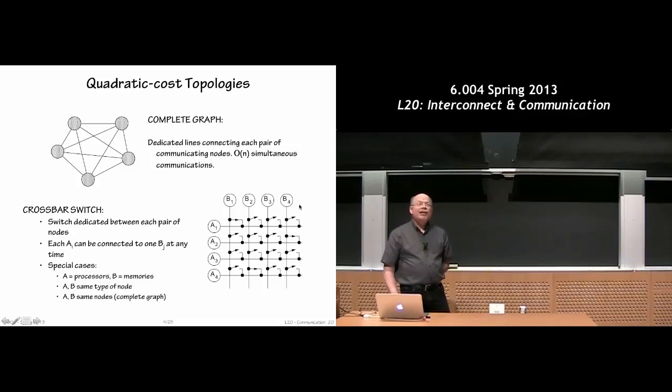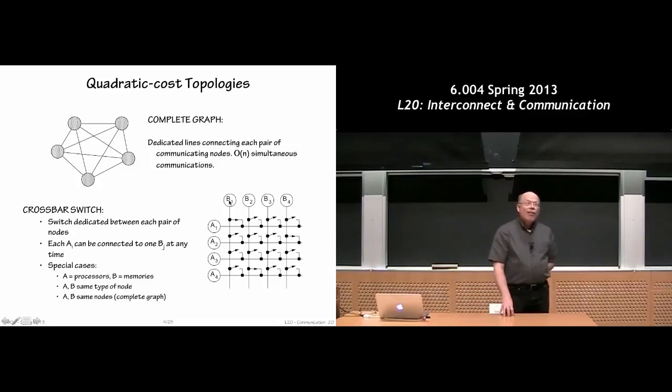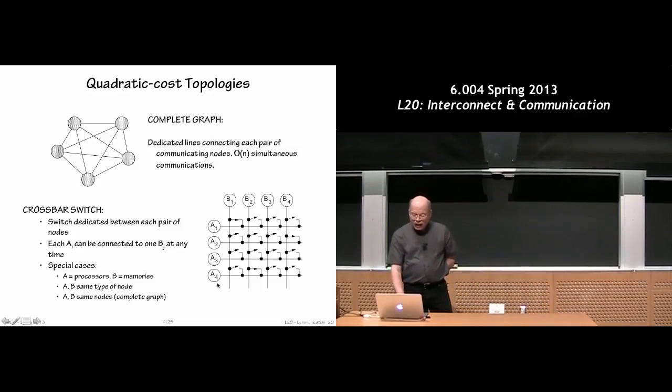So this is one of these probabilistic things, where depending on how you engineer the synchronization and communication protocols, you can make a balance between getting very high throughput through a crossbar, or basically everybody trying to access B1, in which case the crossbar really turns out to be a bus, where we all have to line up and communicate one at a time. But in a large system, it's unlikely that everybody will want to get the same memory location at the same time, particularly when there are caches here buffering up most of the transactions. So crossbars are very popular in the so-called small SMPs, symmetric multiprocessors, that have 2 or 4 cores. They often have a crossbar switch to deal with things like that.